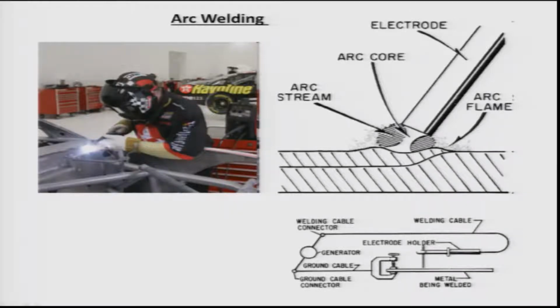Basically it is nothing but a tungsten electrode. Normally it can be used to generate only the heat, and sometimes we also use a feeder or feeding electrode which will melt and allow us to join the two metals. Here you see two pieces of metal getting joined together using an arc flame. In this situation, only a small amount of liquid is generated between the two pieces of metal, and because the liquid is in contact with the two pieces, there are an enormous number of heterogeneous nucleation sites present on both surfaces. So solidification starts with the heterogeneous nucleation of these grains.